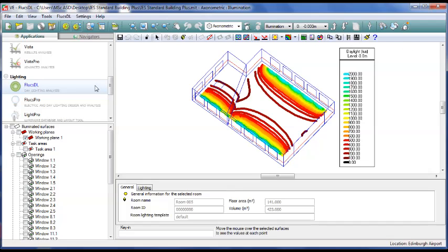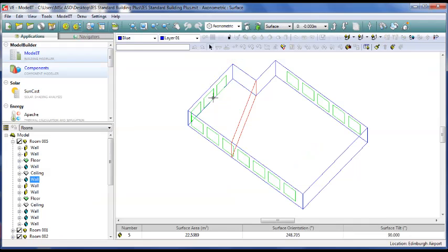And what I'd like you to now do is to go back up to model it, change the material on that to something like aluminium, something that's a bit more reflective, and see how that affects the light levels, and then put another partition in and see how that affects the light levels and play around with the materials between them. And that can be the start of you working up how you're going to deal with your own models.